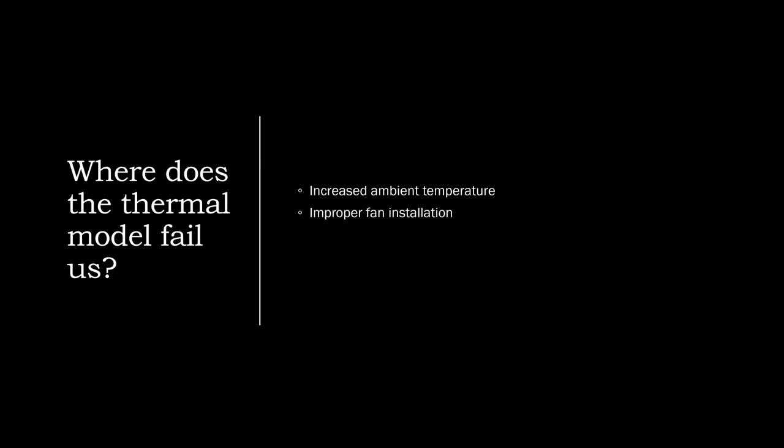Additionally, I spoke to somebody about a month ago who had this happen, and it's a very unfortunate situation. But the motor rewind market is a competitive place, and sometimes there is turnover in these type of shops. And there was a fairly substantial motor that went into a paper mill, and after it was rewound, the fan was put on backwards. And the thermal model, of course, will not account for that.